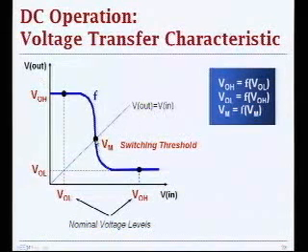That is the threshold that will be related to switching events in a gate, as we will see later in the study of systems with or without feedback. And keep in mind, this switching threshold doesn't have anything to do with the transistor threshold, the threshold of a transistor used to implement a function.